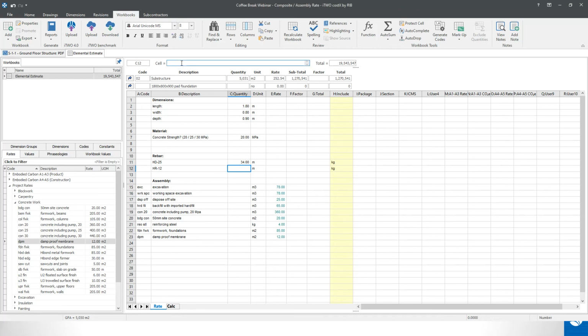We'll click into the formula field and we'll commence the formula by calculating how many stirrups there are running in one direction. So again, we'll use that round one function, open a circular bracket, and we're going to need to refer to the length of here. So I'll just hold down Control and click on cell C2, divided by the spacing of the stirrup. So let's say the spacing is 300 mils in that case, so 0.3. And then we'll close that bracket off over there.